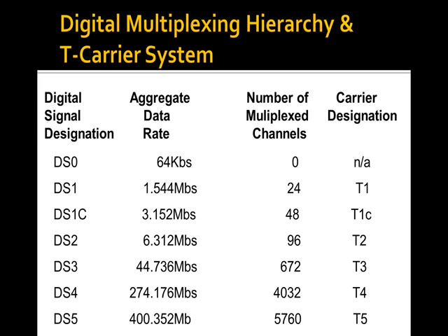So realize where we are, take a breath, and we're going to look at one more little piece here. We have moved from an analog audio signal, coded it, and figured out a way to move a lot of those voice channels over a multiplex channel. Why would we do that? Remember that we had two goals that we were going to try to address. One was noise and attenuation, right? Analog circuits inherently have attenuation involved in them. You inject a signal into a copper media. Some of that energy goes into heating the wire sooner or later, meaning as you move further and further down a wire, that signal gets to the point where you can't detect it. There's not enough power there to differentiate it from the noise, which brings the second issue up, noise pickup.